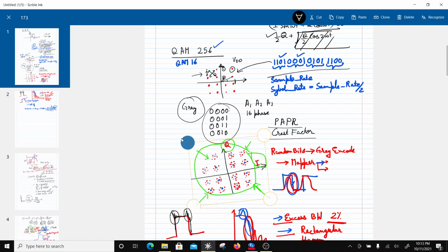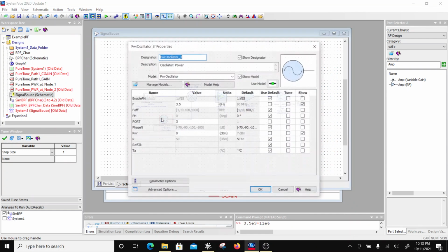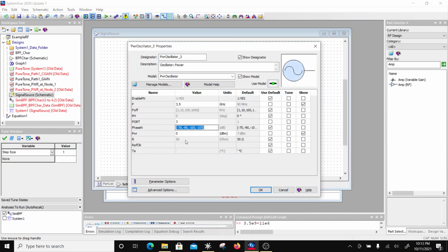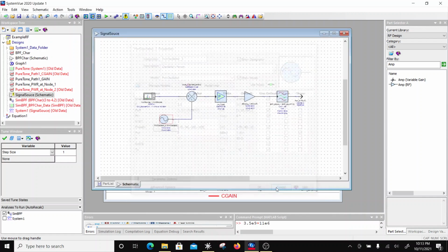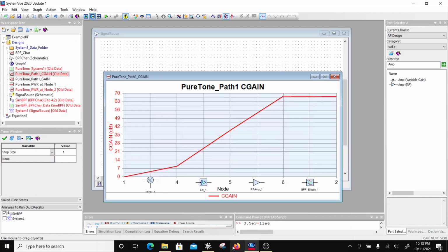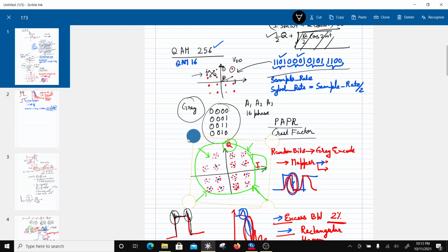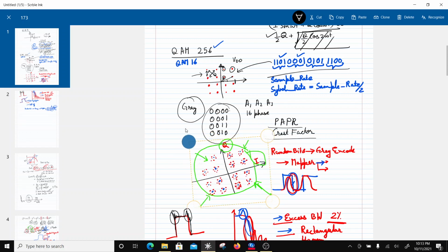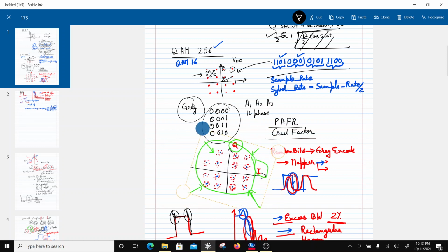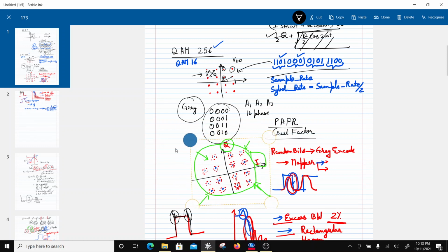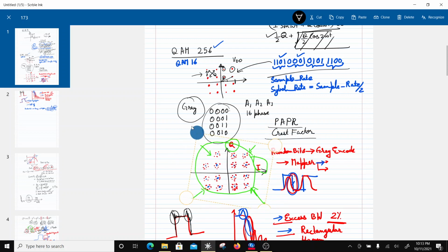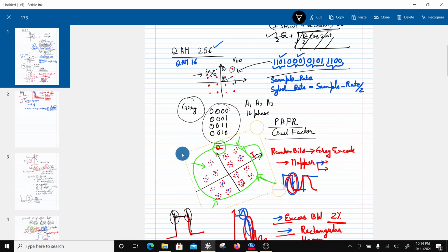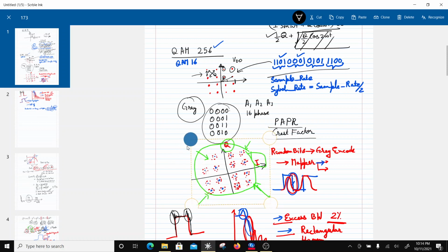They're going to rotate. But then what the phase noise is going to do, so if you see here, this one has the phase noise characteristics over here, and maybe later I'll show you what that is going to do. It is going to make your constellation dance like this, and this is not statistically predictable because the phase noise is not statistically predictable. So if it dances like this, then the bit error rate would suddenly bump up, or you will have the system compromised completely because the phase noise is not predictable.